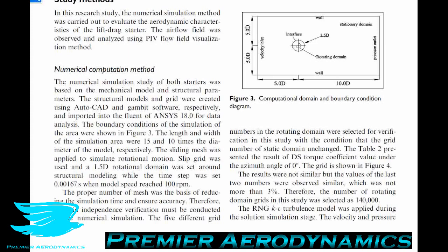The sliding mesh approach is where you literally have this rotating domain here, and with each time step it will rotate around physically. Because this domain effectively is isolated from the rest of the domain, the cells in here can just rotate and slip across, and then the information from this domain gets shared with the larger domain that it's effectively part of in the grand scheme of things.